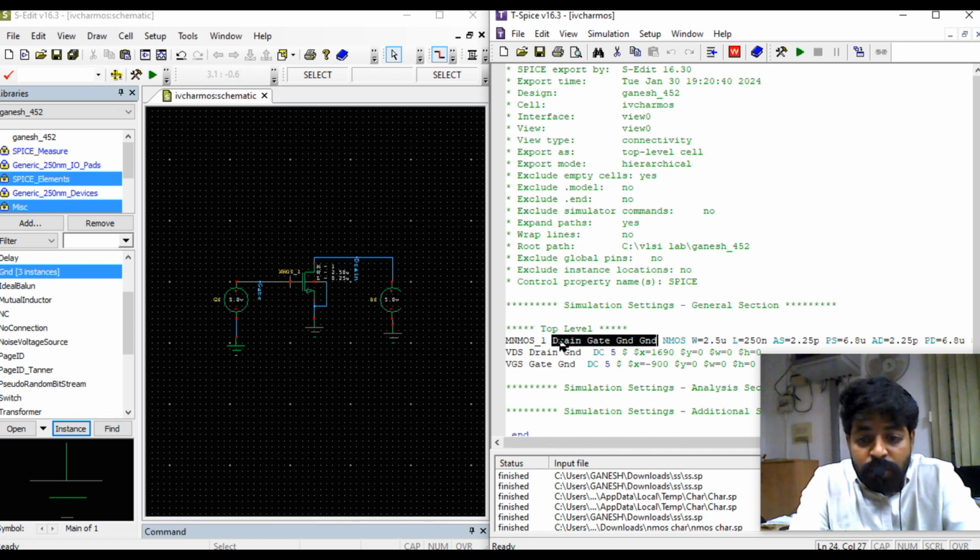So that is how the node notations of a MOS transistor, that is the gate level netlist for the MOS transistor. And after that, how the NMOS transistor has to work exactly will be shown as a model name for the MOS transistor, with the width of this much, length of this much, and the remaining parameters will be mentioned over here, and that will be the first component.